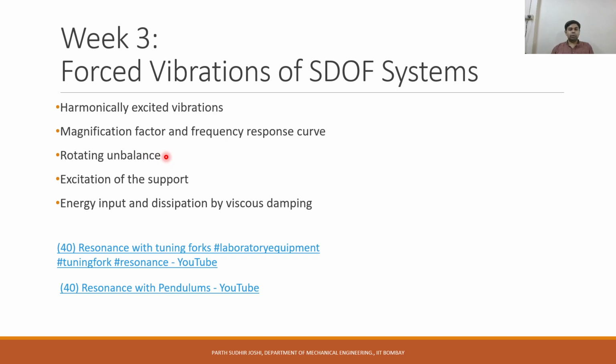For example, if a turbine blade has some eccentric mass present in it, and the frequency of vibrations caused by the rotation speed actually matches the resonance frequency, then there are chances of catastrophic damage to the turbine.